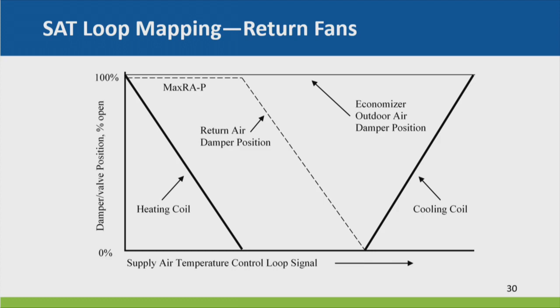The return fan is blowing the return air; what's left over is outside air. And it doesn't matter whether the damper's open, closed, or anything else, you're going to get the same outside air if you're controlling all these things with the damper wide open or not. So you don't even need a damper other than when the system turns off and you want it to be closed when it's off. So very interesting change there. And of course, this saves energy too, because now that damper is wide open and you don't have any pressure drop across the outside air damper.